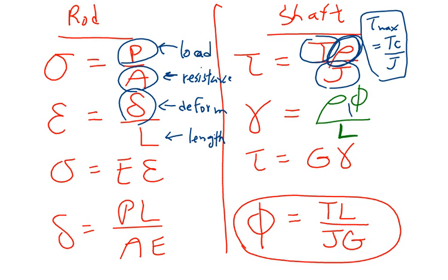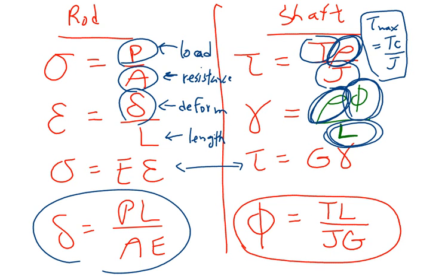It's this value phi, our angle of twist, and there's length. And of course, just like with stress, we need this term for rho, the radius, because our strain is also going to vary from 0 at the center to a maximum value at the outer edge. All right, then of course we have Hooke's law. No need to discuss those. And then you combine the three equations to get your total deformation equations.